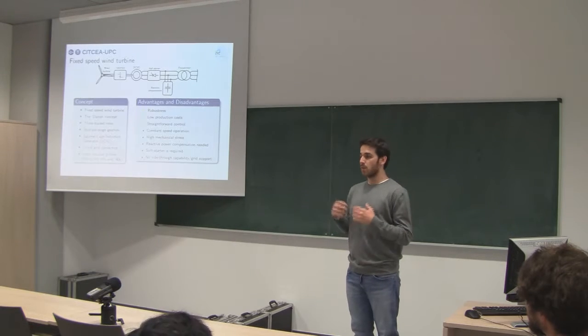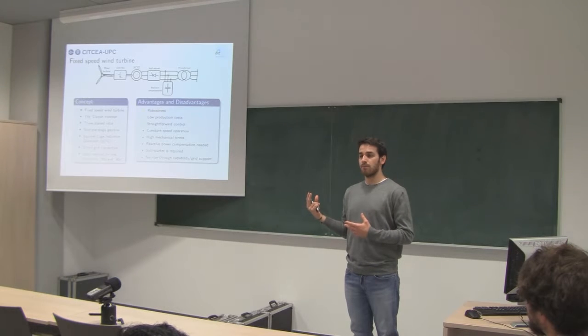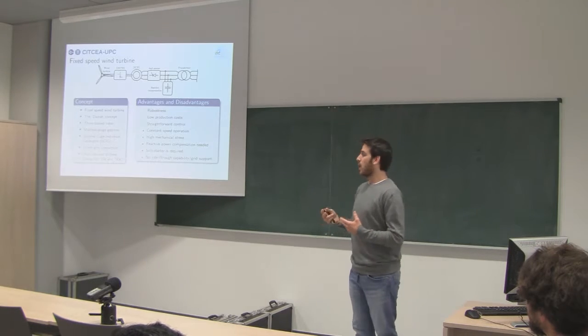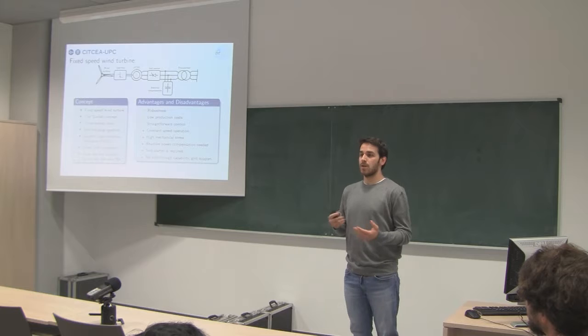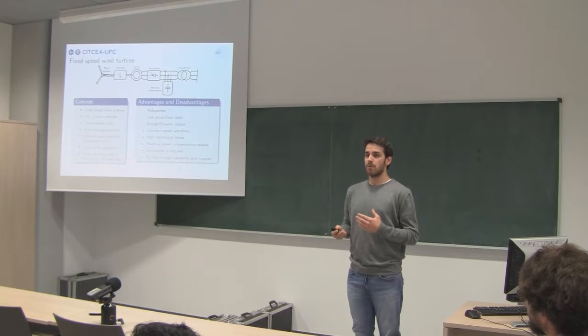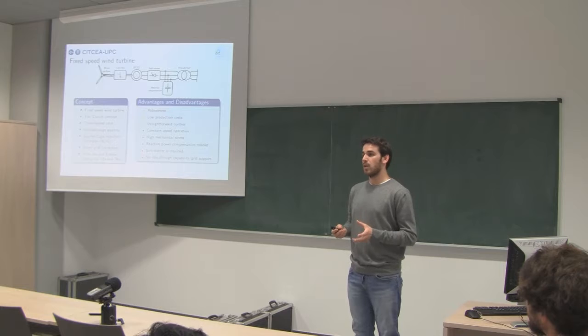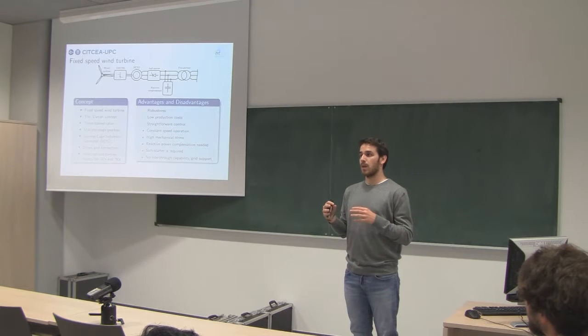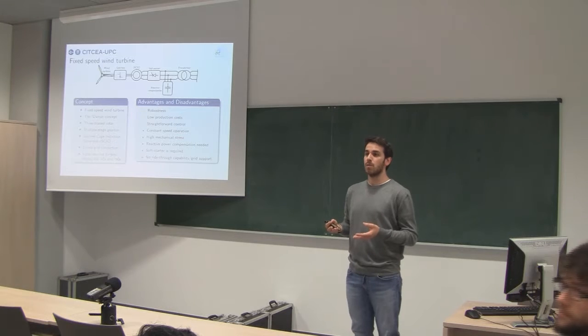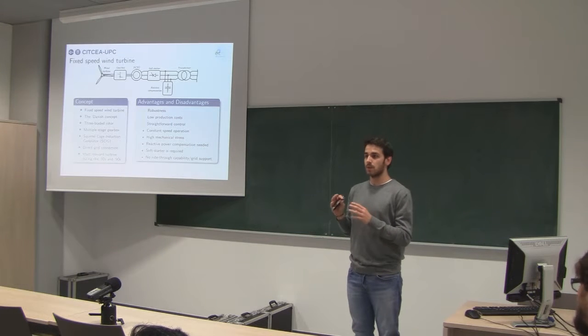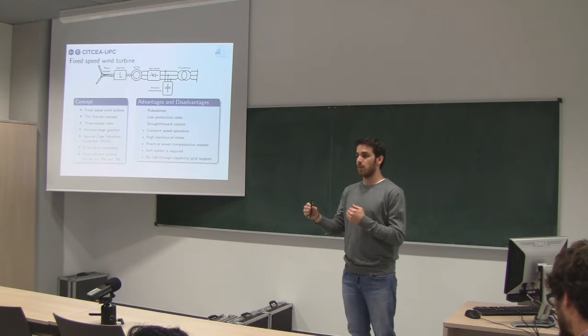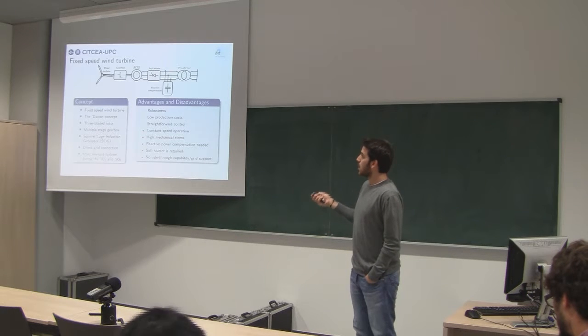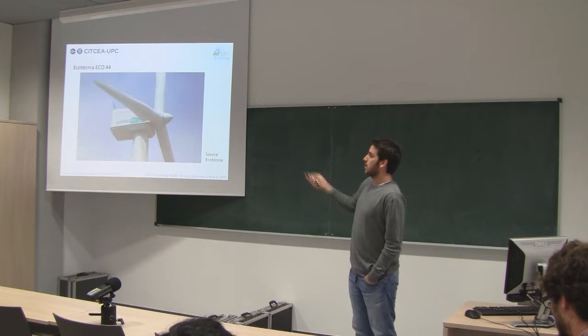As we had more and more wind power installed, we started to see that this kind of configuration was a problem, and the transmission system operators forced the technology to evolve to a different topology with power electronics, that can, for example, during a voltage sag, give some grid support. Okay, there is another similar concept to this one, which is, well, just a picture.